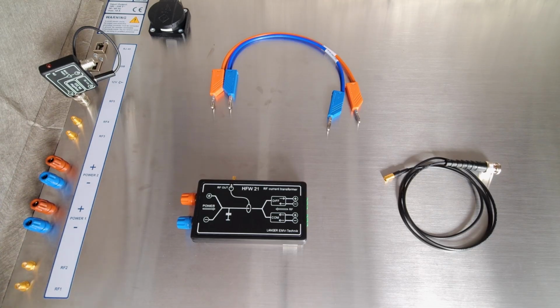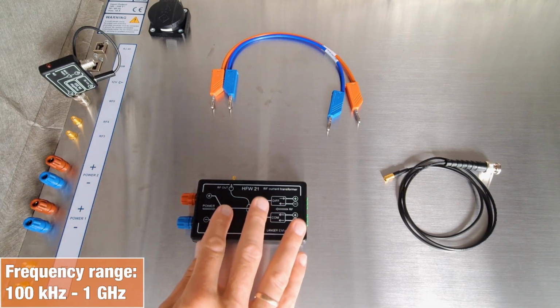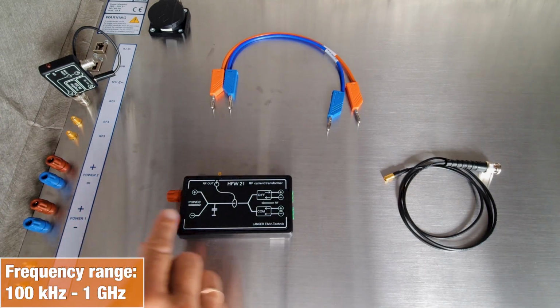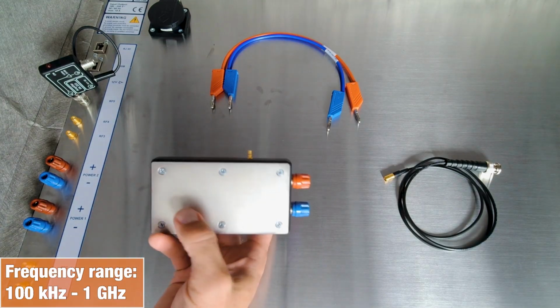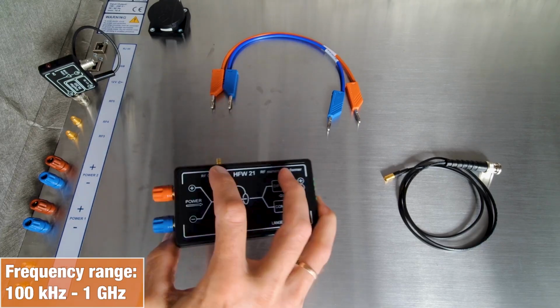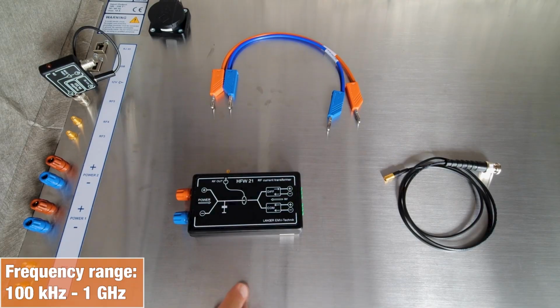When you have an application with a DC power supply, you have to bring this RF current transformer box here into the power supply of the device under test. You can see here that the RF current transformer has a metallic bottom side, and with this metallic bottom side you have to place it directly onto the ground plane.